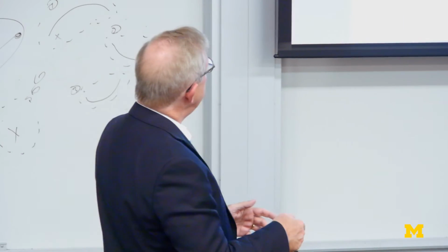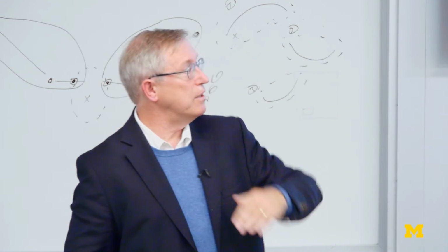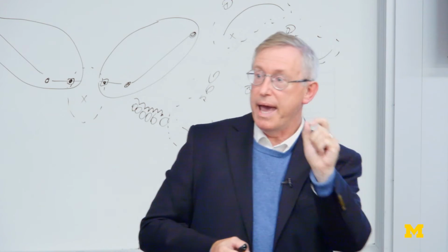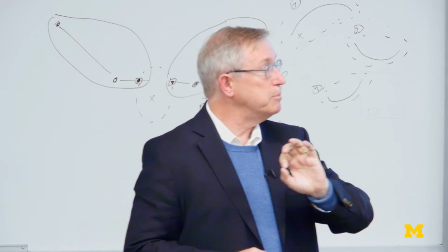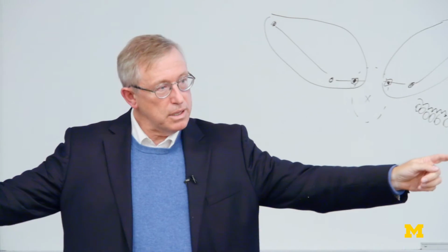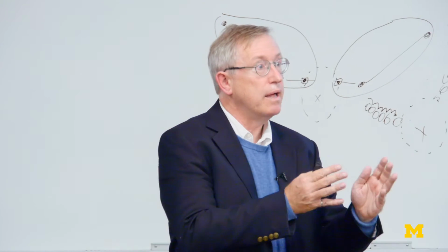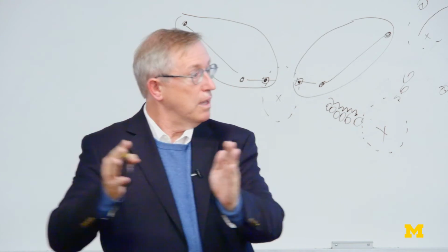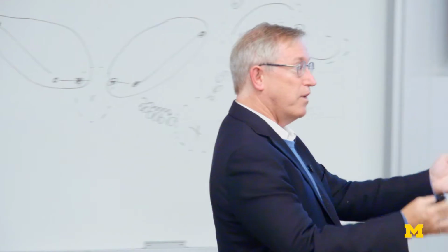And if you have distributed amplification, this Raman-style amplification I was talking about, a little bit of noise would be added in our numerical simulations at the end of each of those little segments. Okay? So a 1,000-kilometer transmission span might be divided up into several hundred pieces, or even 1,000 pieces. 1,000 kilometers divided by 1,000 would be 1 kilometer each, right? That kind of idea.